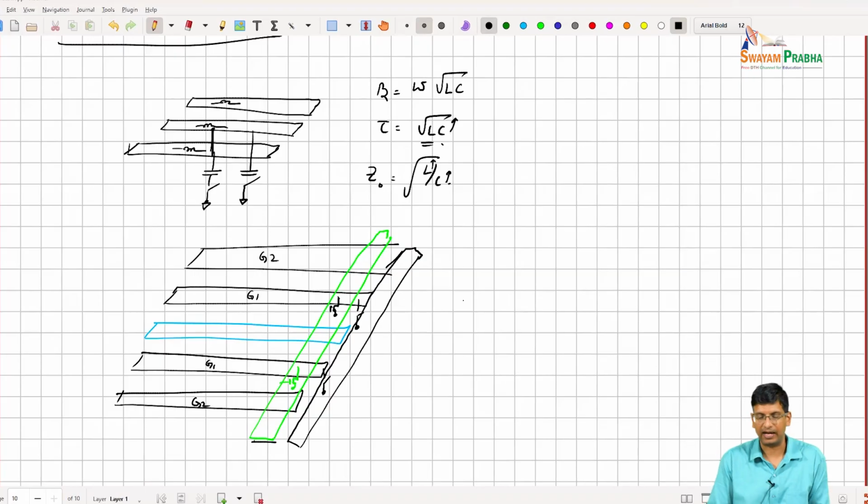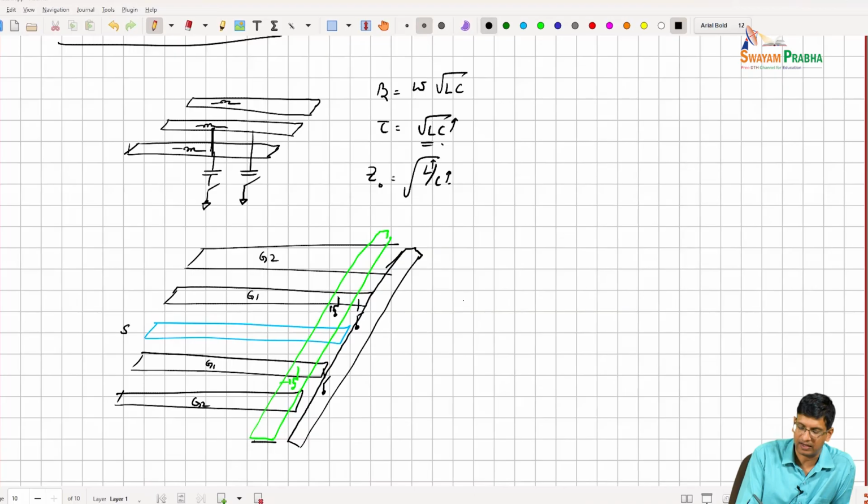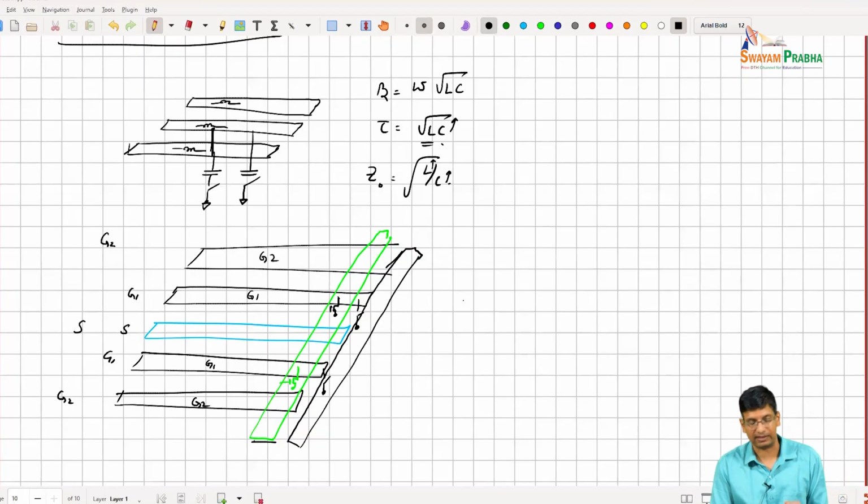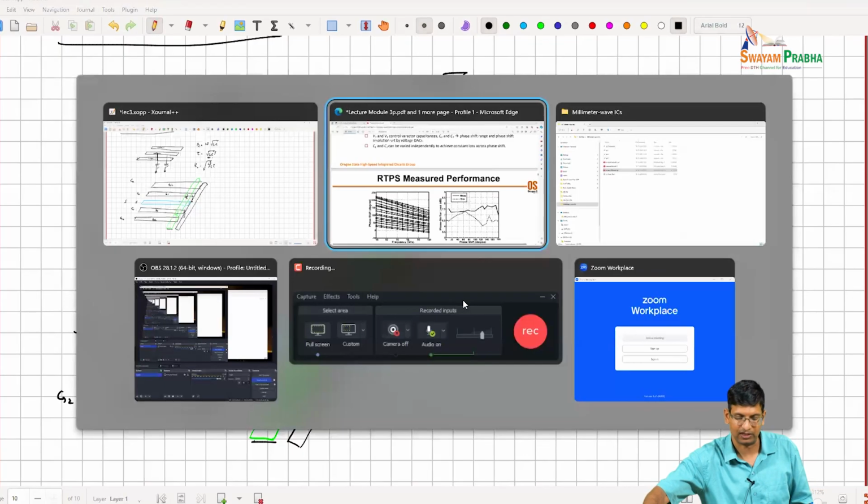So I'm creating modes of operation where either I have a situation with SG1 G1 or a situation with SG2 G2. So in addition to the capacitance switches, I'm adding these switches as well. Using this approach, I can try to keep my impedance constant when my load is changing.